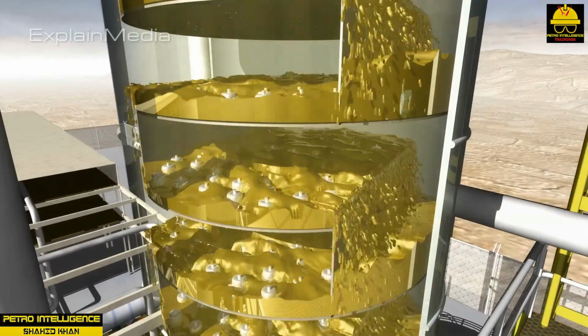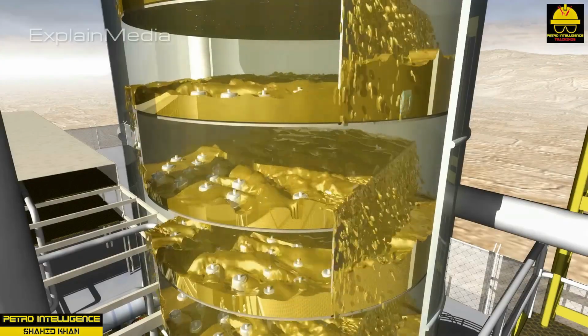A reboiler maintains the heat balance on the tower by reboiling the components that have given up some of their energy during the distillation process. A kettle reboiler or thermosiphon reboiler is typically connected to the bottom of the tower. However, reboilers can be attached to the various side streams on the column. A kettle reboiler has a special vapor disengaging cavity that is designed to remove the lighter components from the mixture and return them in the form of heat back into the column below the lower tray. Heavier components in the liquid flow over the weir in the kettle reboiler and out of the tower system. In contrast, a thermosiphon reboiler will vaporize the liquid and return it to the tower operation.